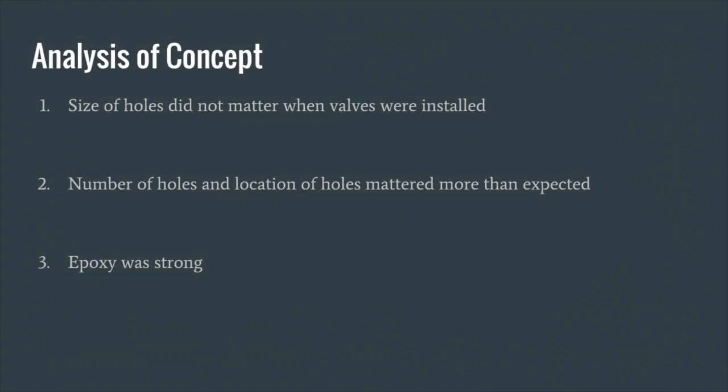So for the analysis of the experimental results, the size of the holes did not matter when the valves were installed. The valves were sticking up slightly from the surface of the holes in the container, so they actually pushed away the particles while still allowing water to flow through. When there were just holes and we were doing the tests with the particles, the particles would fit into the holes and sink into them, and that's what caused the clogging in the bottom.